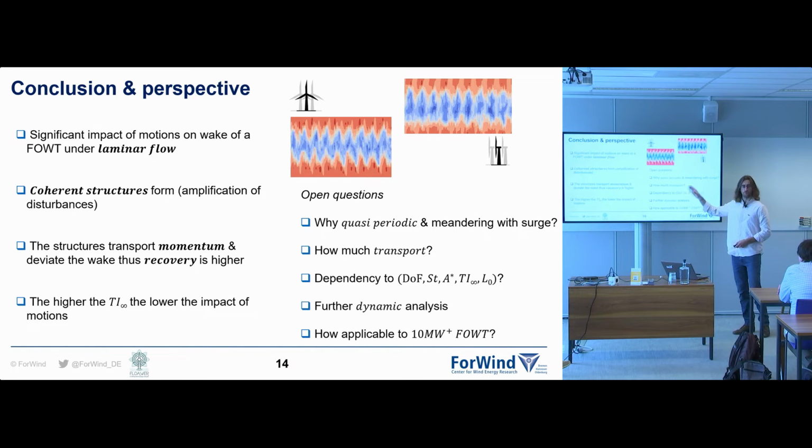What we show with this 2.5 years of research is that motions of a floating turbine do impact the wake on the average values, at least when the flow is laminar. Here, I also stress that we did some tests with turbulence, and we noticed, and this is also from a lot of studies, that when there is turbulence in the inflow, the higher the turbulence, the less the impact of the motions. And the question is, what is the region at which we still have a great impact? This is still something that needs to be investigated.